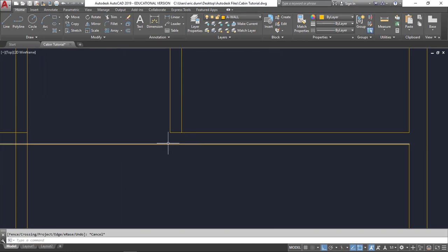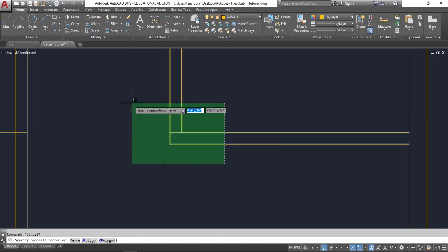So this wall should connect. Again, I could use the extend command to connect those. I don't want to drag that. That's typically bad CAD because things could go haywire. I could move things crooked. It might not work out right, and we'll find out later on in the drawing that something wasn't right, and it complicates things. So I'm going to use my fillet. I'm going to click here and here. That cleans that up. And I'll need to trim that.